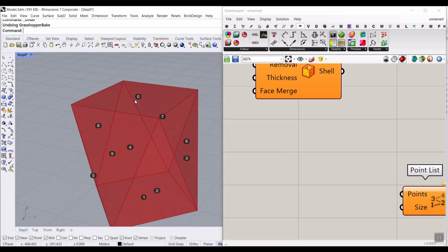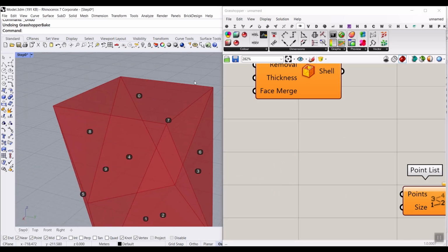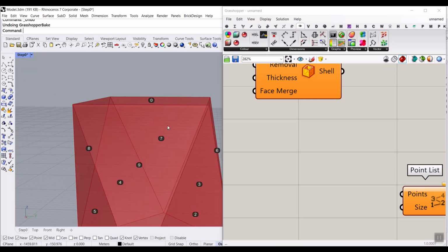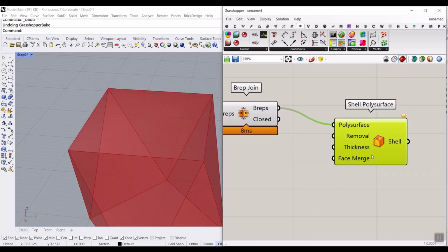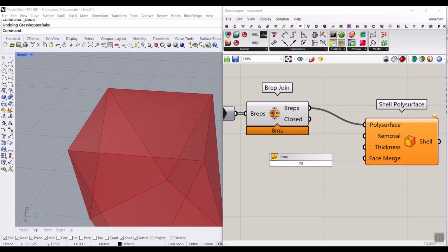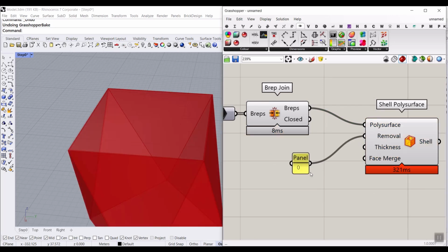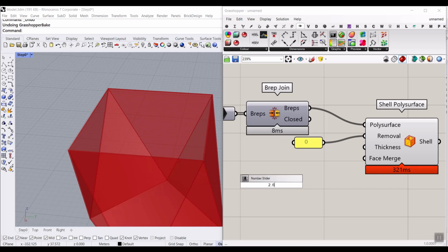And you can see that the first technique which I've explained, you give the top first, then the bottom, is working, and it's actually the first face. And that is really great because we can just go here and say 2/0 and give it to the removal. That's it. Just delete this title, maybe. And also the thickness, which we can change parametrically, 2 to maybe 6 with 2 decimals. And I can give that to the thickness.